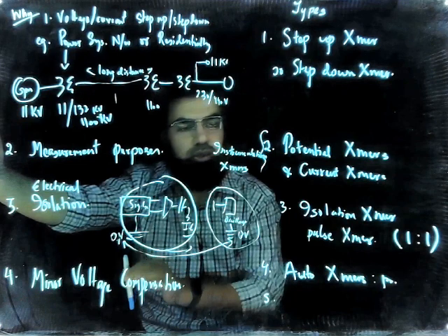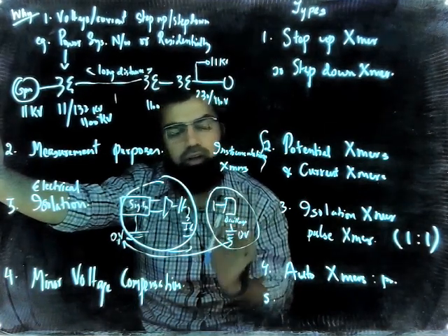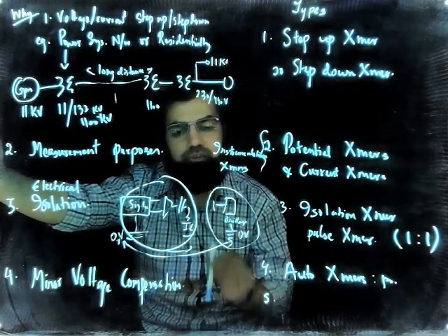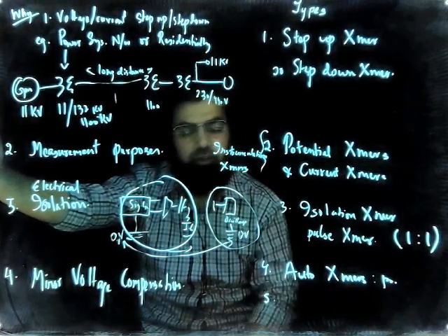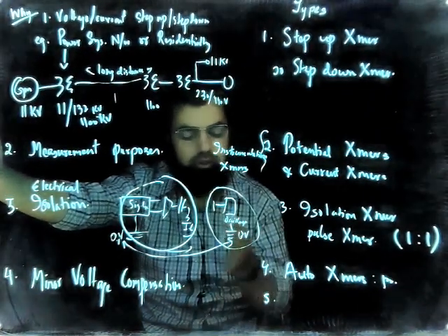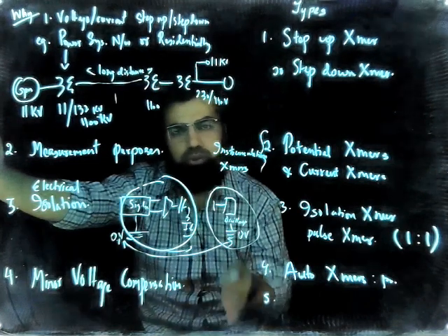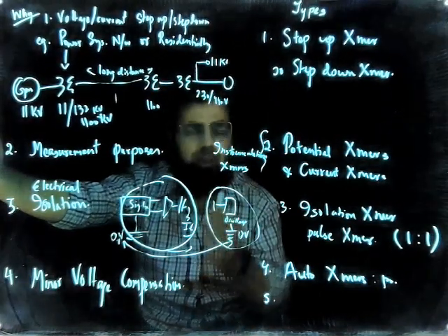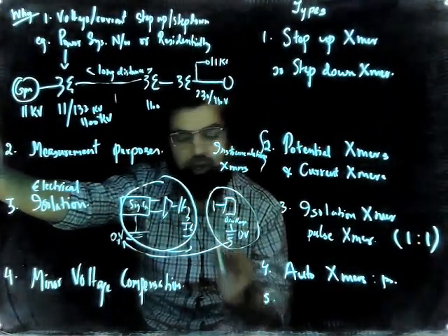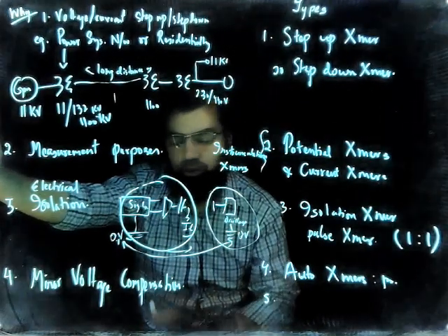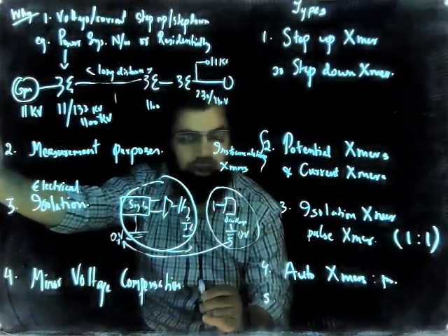Auto transformers are required where you require a very minor amount of variation between the primary and the secondary voltage sides. There, from 200 to 230 volts, 210 to 230 volts, these are small changes that we actually require. We do not need transformers for such purposes. We can use auto transformers.